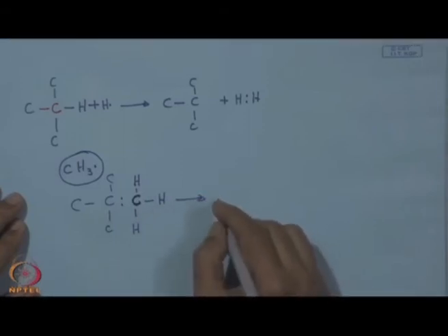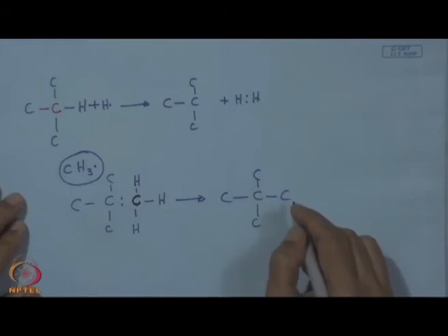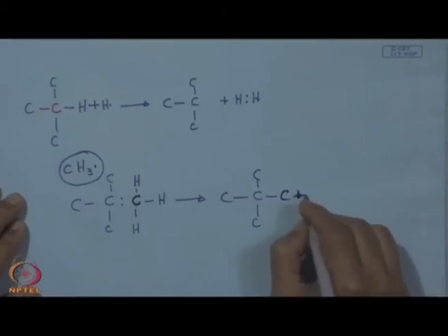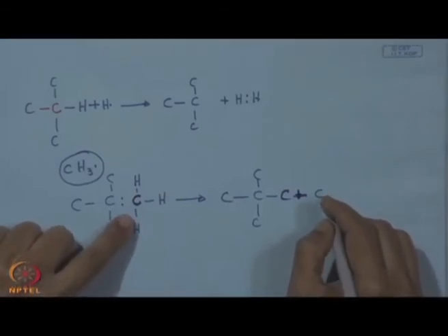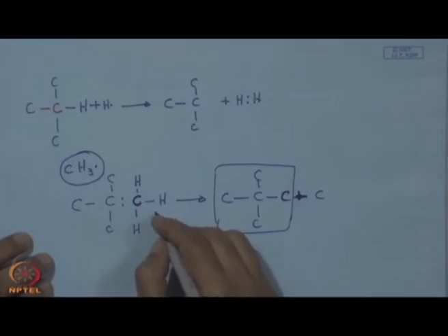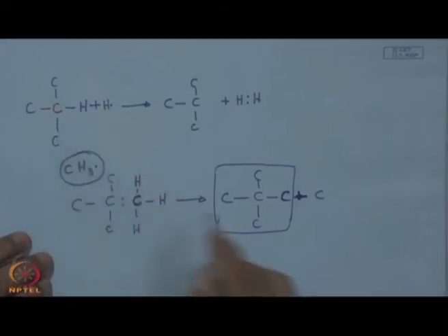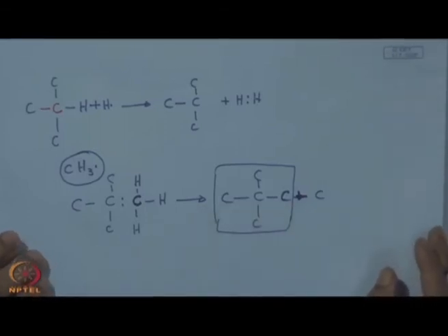So, what we finally see here is that we have a complete lattice of diamond. That means this site is no more vacant, and we have here this C, and this will keep on moving in every direction, and we get this complete filling of this atomic site. So, on every location wherever you have that removal of hydrogen, that will be filled in by this methyl radical. So, this way the diamond coating will keep on growing. So, this is actually what we know as CVD reaction.